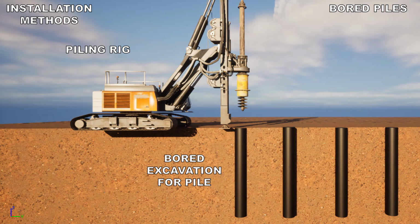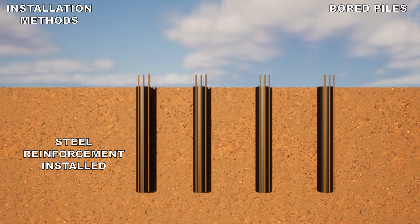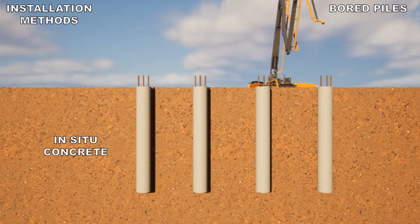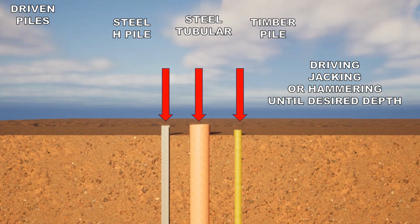The method of pile installation is an important consideration in both the design and construction phases. Individual piles are installed using specialist plant called piling rigs. Bored piles are installed by first extracting the soil volume in the proposed pile location, and then forming the pile in situ using concrete. Driven piles are instead pre-formed using steel, precast concrete, or timber, and installed in the ground via driving, jacking, or hammering.